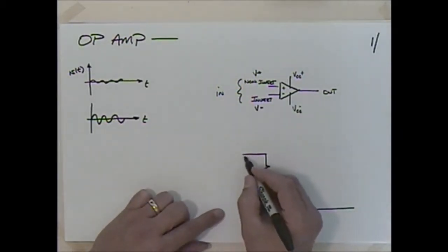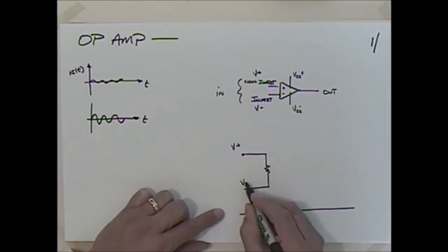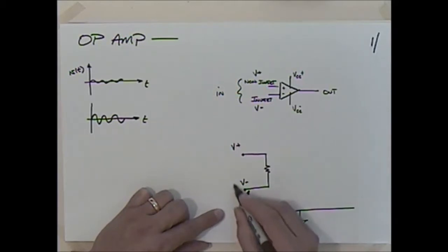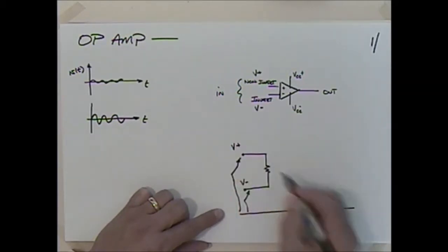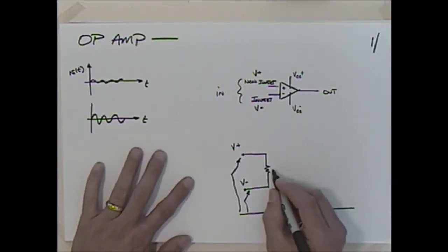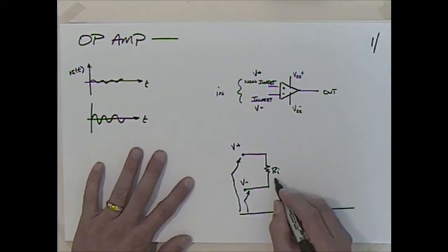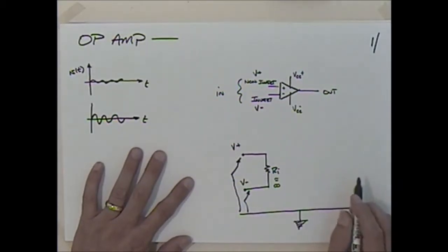And this would then be our V plus, and this would be our V minus. So from up there to there is V minus, and then up there is our V plus. And we're hoping that this input resistor, Ri, we'd like this to be as close as possible to infinity. We would like it to be very large.